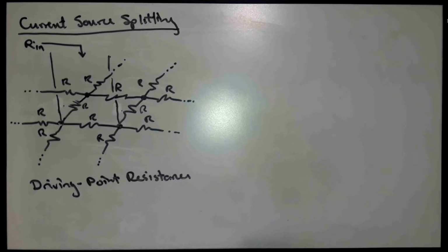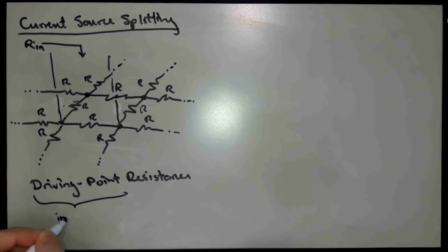When you have a mixture of voltage and current at the same location. So it's not a transfer characteristic in the same sense as you have an input and an output at different places in the circuit, but you're driving a current into, let's say, 2 wires in the circuit, which is a port, and the response of the circuit is the voltage that develops at that same point across that same port. Okay, and that's what this driving point resistance is. So a driving point transfer function, input and output are at the same place.